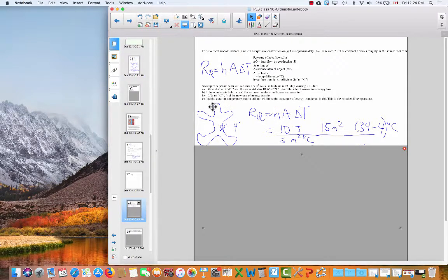Now what happens in practice is that your body will warm up the air around it a little bit. That warmer air is less dense than the surrounding cold air, and the warm air will rise. So you can actually see a little heat plume rising away from your body if you look with sensitive infrared instruments. And then that warmer rising air is replaced by more colder air, which then again absorbs energy from your body. So there's a loss of body heat to the environment, and we calculate it in this way.